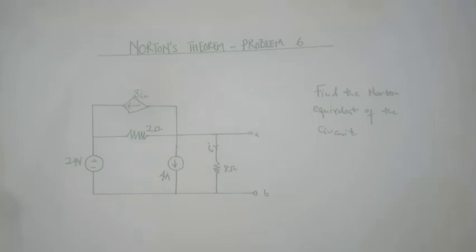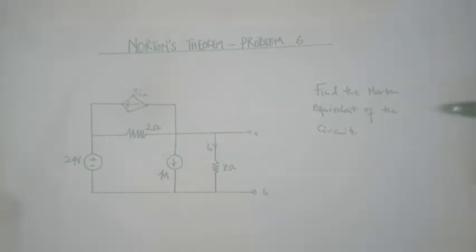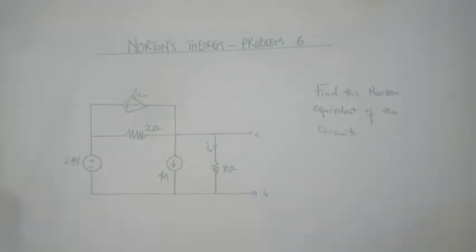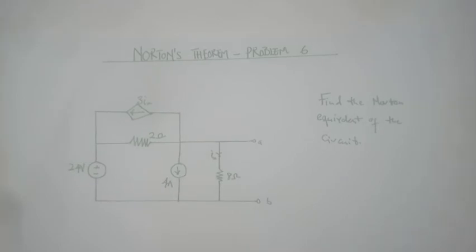Welcome to another video on Norton's theorem. The goal is to find the Norton equivalent of this circuit, and to do that we need to find the Norton current and the equivalent resistance when all the independent power sources are turned off.